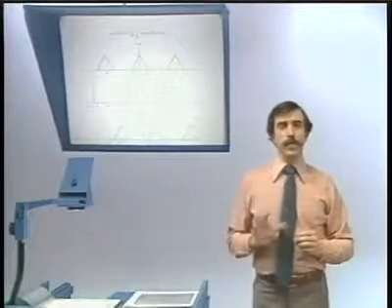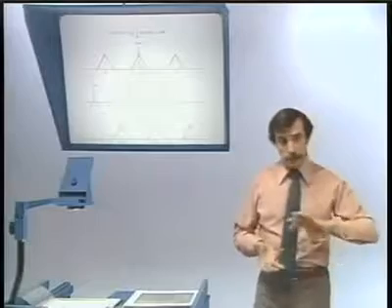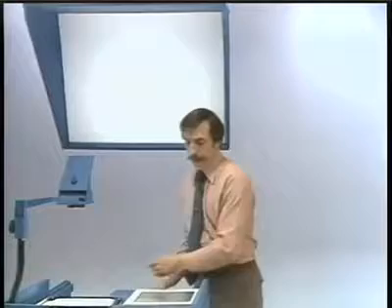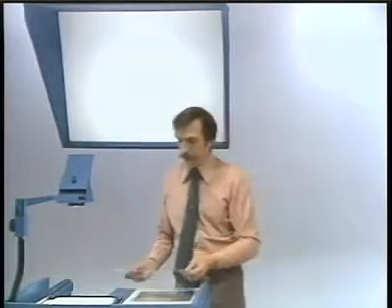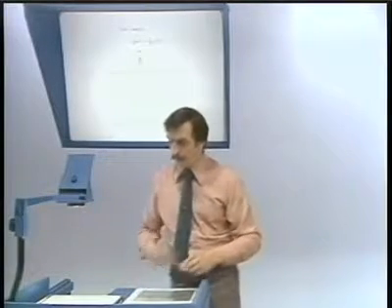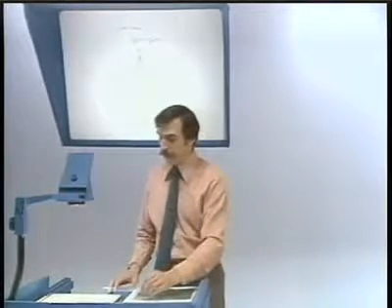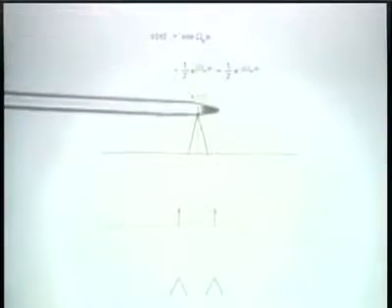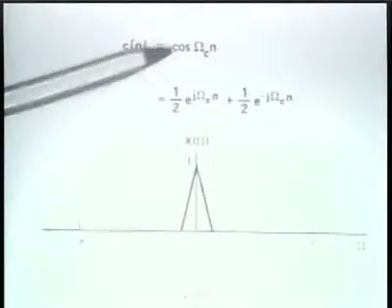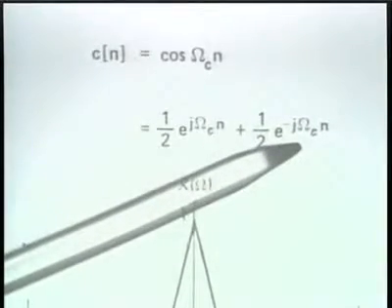Okay, now let's consider the case of a sinusoidal carrier in discrete time. And again, things very much parallel what we saw in continuous time. And again, as we look at the spectra, I will choose a phase angle of 0, mainly for notational and analytical convenience. So in this case now, rather than a carrier signal which is a single complex exponential, it's now a sinusoidal carrier, and the sinusoidal carrier is the sum of two complex exponentials.